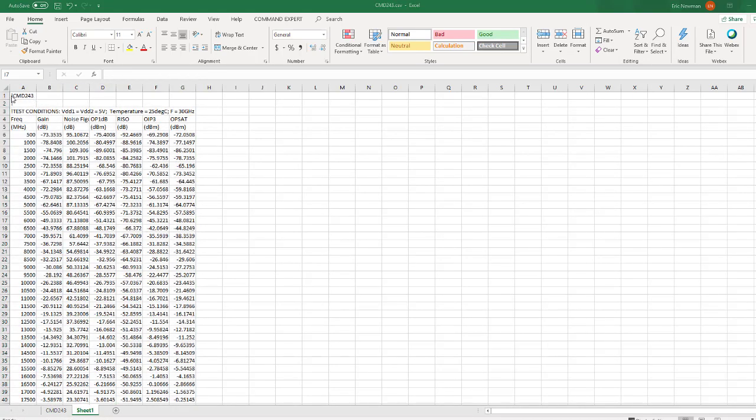Okay, now that we have this data pasted into a new sheet here, we'll make a few modifications. The exclamation point will be recognized as a delimiter to comment away the information on that row. On the second row, we're going to type BEGIN, and we'll call this block DATA. That tells the tool that the next relevant rows of data will be the data that we're trying to take into the multidimensional interchangeable format, the file format that we're going to use in the Advanced Design System.